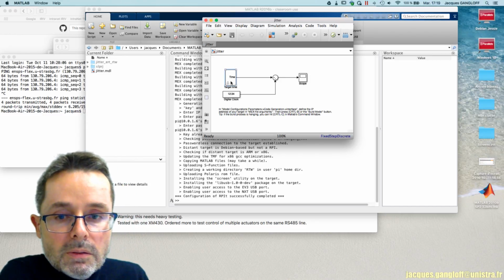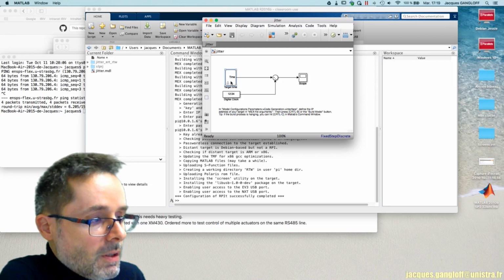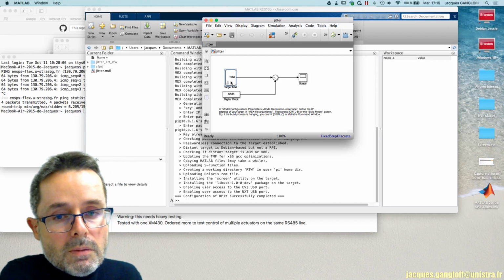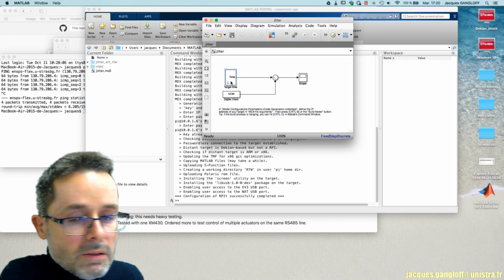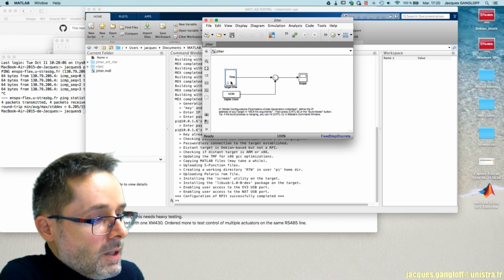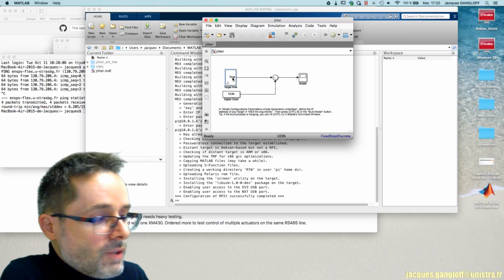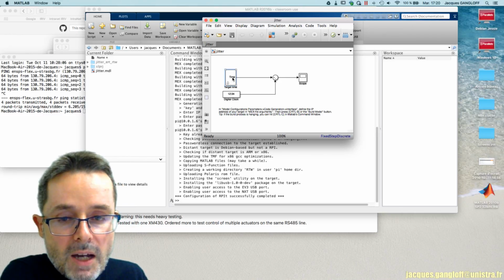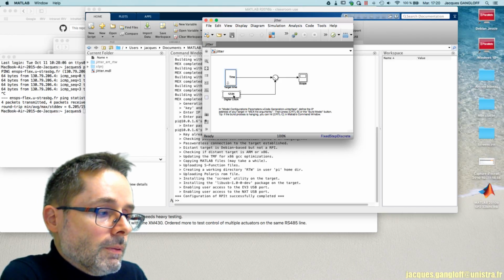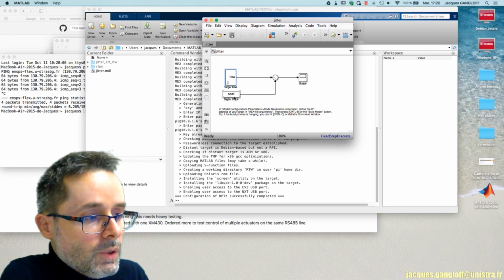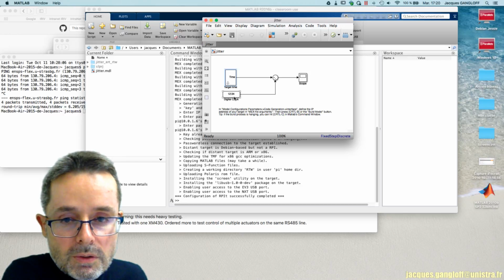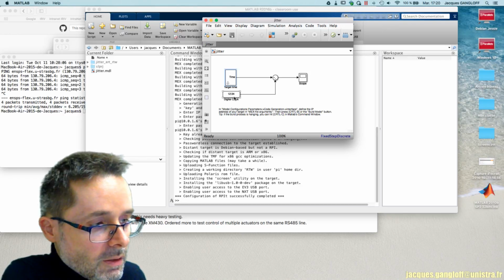This block acquires the time by reading a hardware clock directly on the target. And you compare this value, this time, with the time given by the block digital clock, which is the time on the host, so the time on the machine running Simulink.